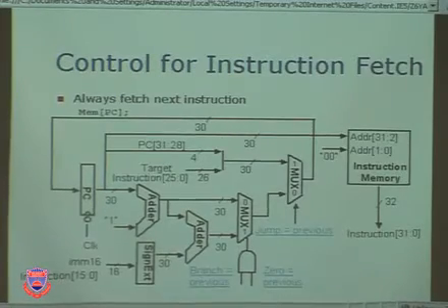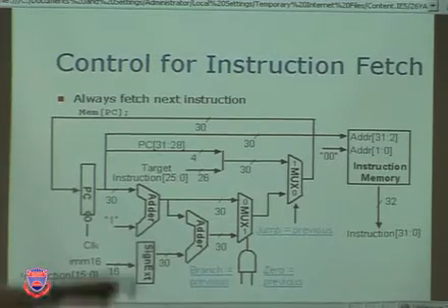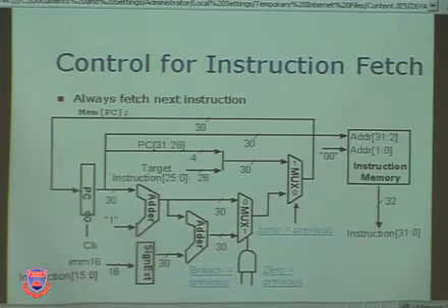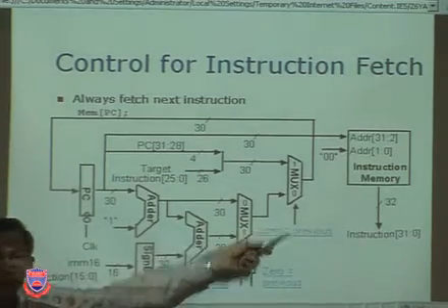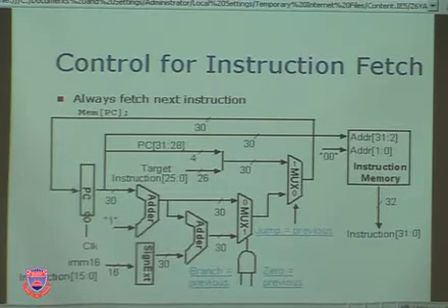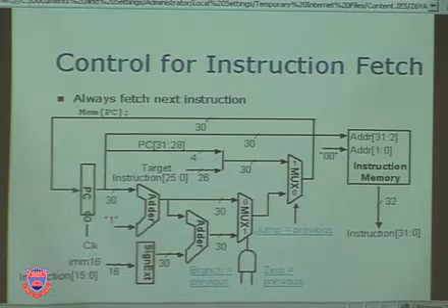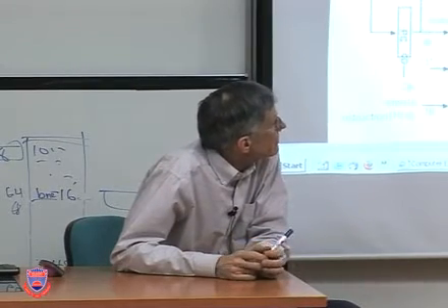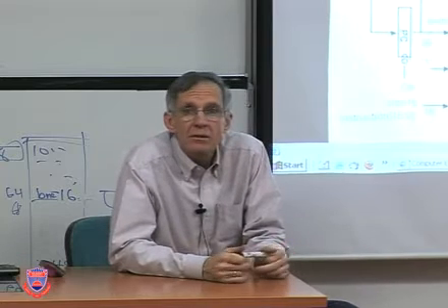All right, so let's go to the instruction fetch unit. This is our instruction fetch unit. We talked our way through this. I hope everybody recognizes that the control signals are this one and this one and this one. Those 3 things here. Now, how come the instruction memory doesn't have any control signal? Looks to me like we just give it addresses and out pops instructions.